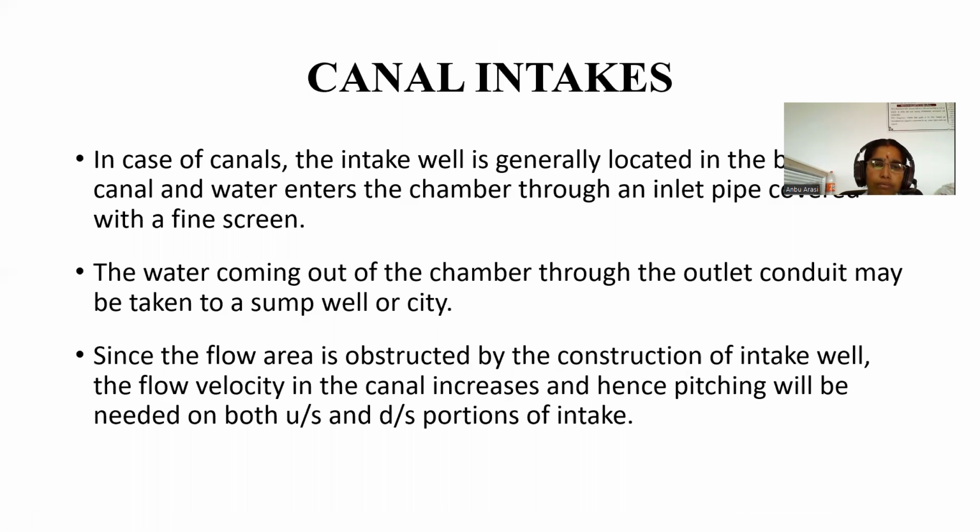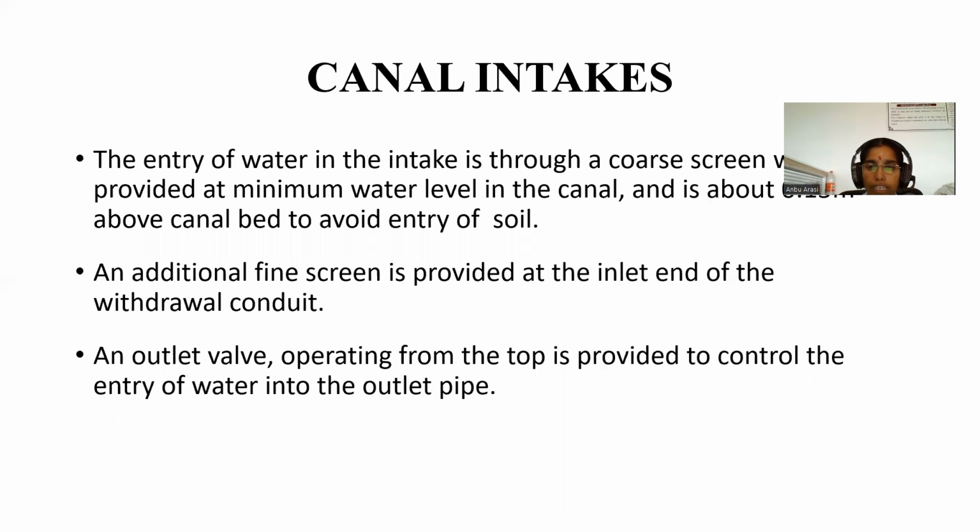Next, canal intakes. In case of canals, the intake well is generally located in the bank of the canal, and water enters the chamber through an inlet pipe combined with a fine screen. The water coming out of the chamber through the outlet conduit may be taken to a sump well or city. Since the flow area is obstructed by the construction of the intake well, the flow velocity of the canal increases, and hence pitching will be needed on both upstream and downstream portions of the intake.